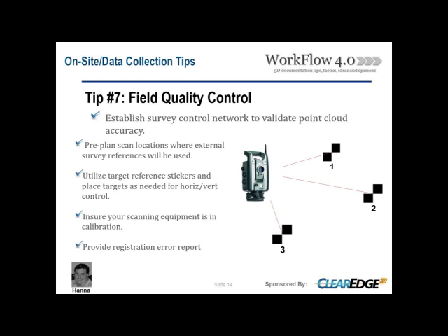Also, make sure your scanning equipment is in calibration. Calibrated by the manufacturer, but also do periodic checks. Make sure it's a measuring technology. Make sure it's measuring within the specifications, and that's really important. And then lastly, provide your client with a registration report so that they can determine the errors and the project's met the overall specification.